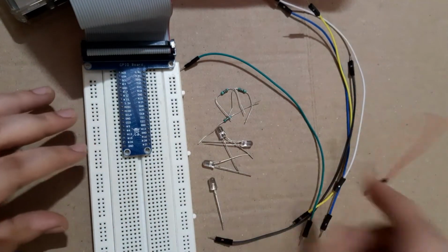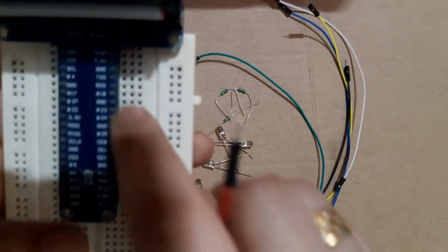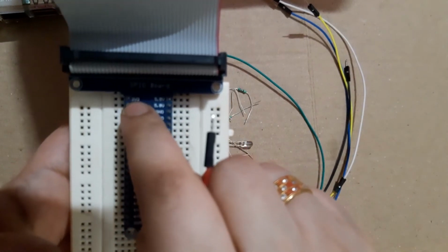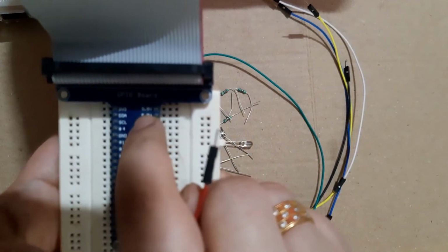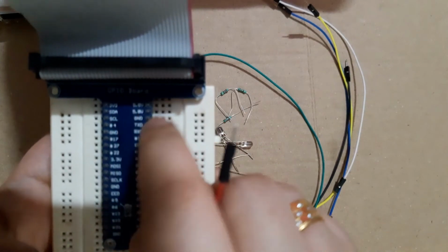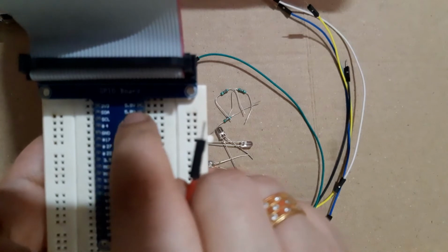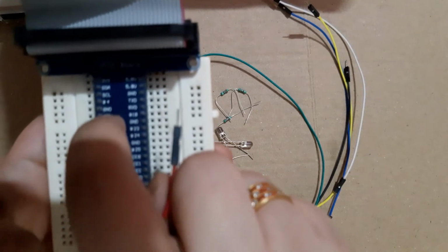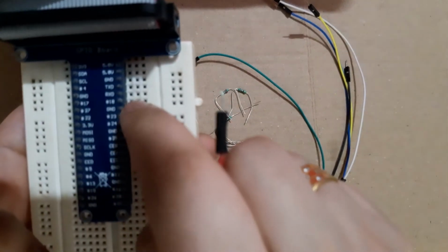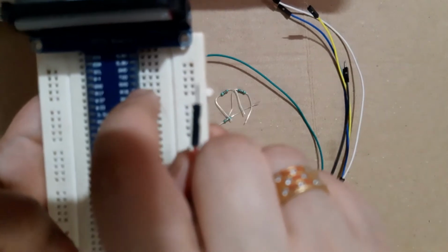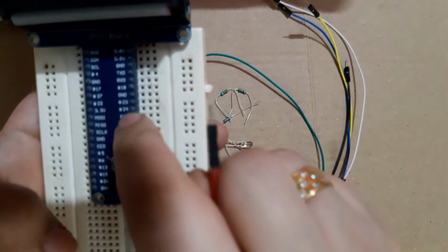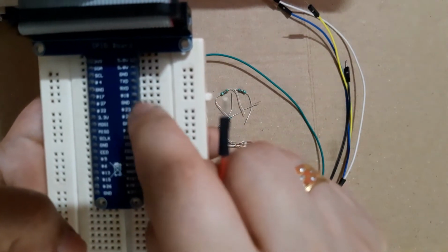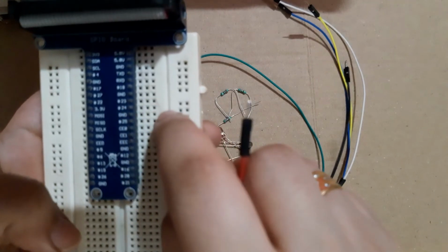Then you can see here that this first pin is plus 3 volt, the second pin is 5.0 volt. Even this fourth pin is also 5.0 volt. Similarly, some pins are marked as ground. Some pins are marked with a hash tag like hash 18, hash 24, hash 23, 25, etc. These are the GPIO pins that I am going to use to connect the LED's positive side.